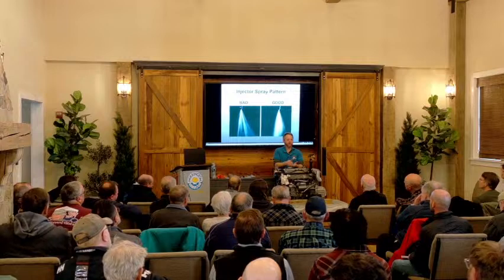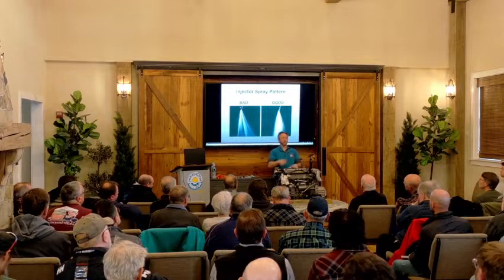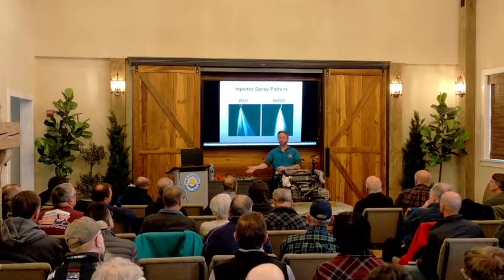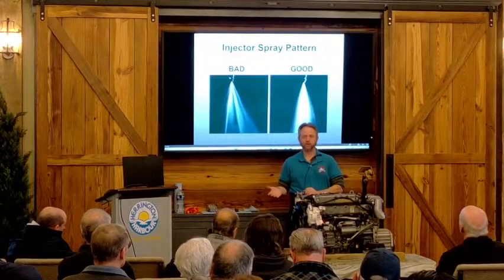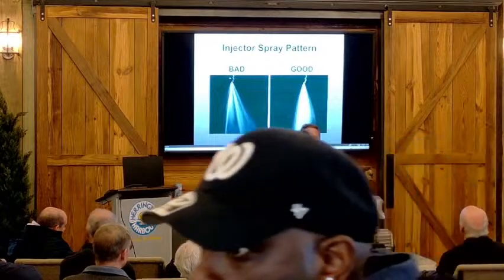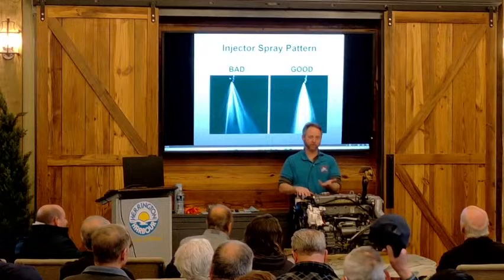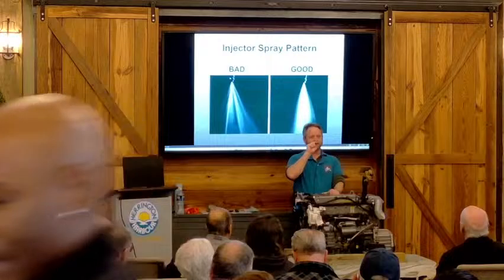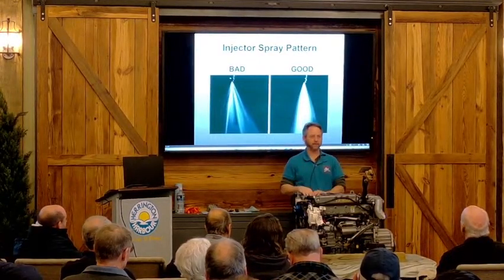Like every time you pull that oil out, send it out. So you hear a lot of people say, I'm looking to buy this boat, I'm going to send an oil sample out of the used boat. Most people who put boats on the market do a service to it before they put it on the market. So you're basically sending out fairly new oil. So it's not going to tell you a whole lot usually. But you want a baseline. So doing one test doesn't really tell you a whole lot unless there's something majorly wrong with the engine.